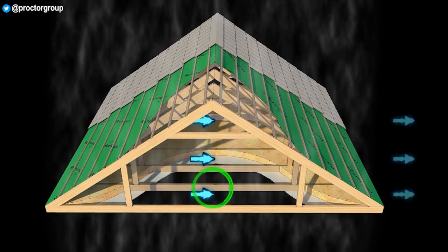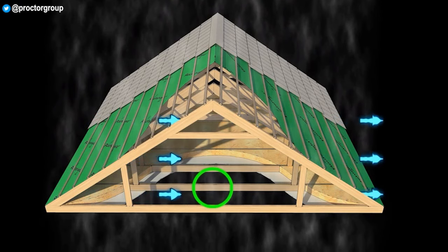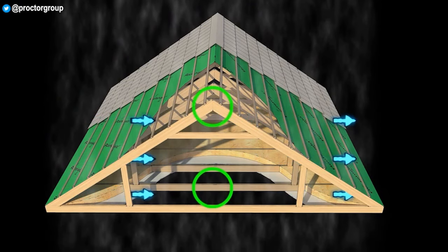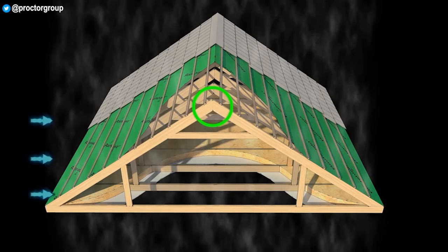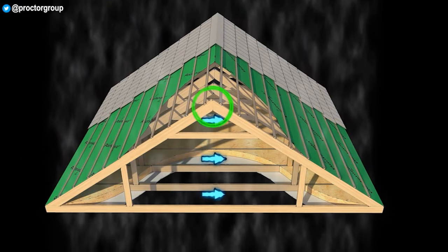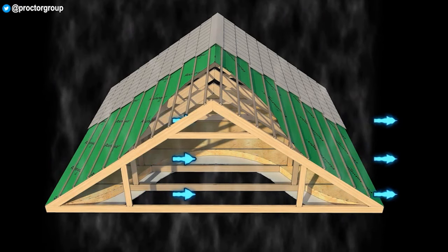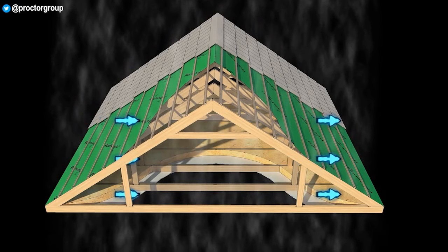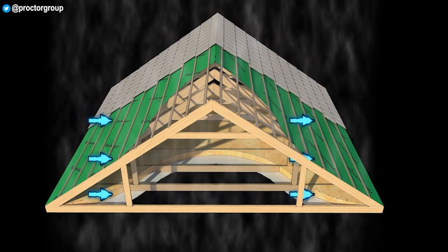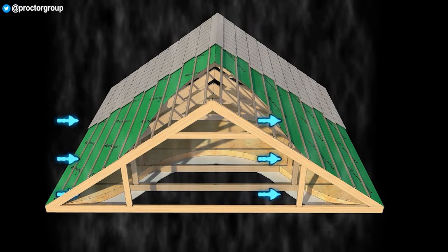This additional permeability means no vapour control layer is required at ceiling level, and no openings are required at the ridge. This type of roof construction provides a simpler and a more robust solution, with less likelihood of incorrect ventilation or ceiling specification or installation. As long as the air open underlay is installed correctly, the risk of condensation will be minimal throughout the life of the building.